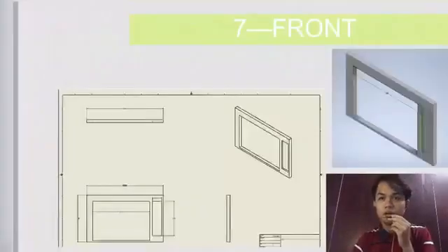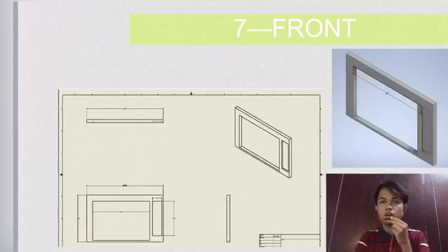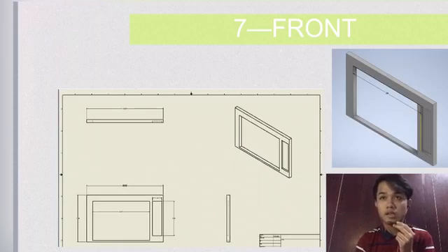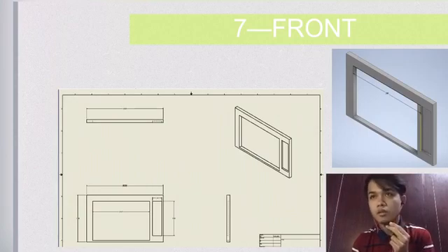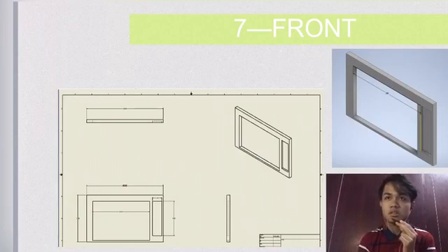Lastly, I will talk about the front, the oven cover. On the front, the length of the cover frame is 19.69 and the width is 11.81. On each side there is a part for the temperature and time adjuster with a length of 8.66 and a width of 2.36.